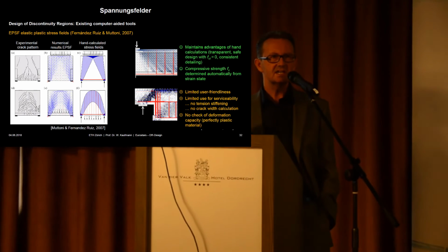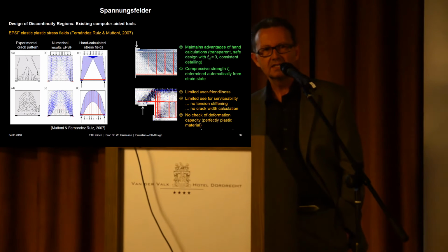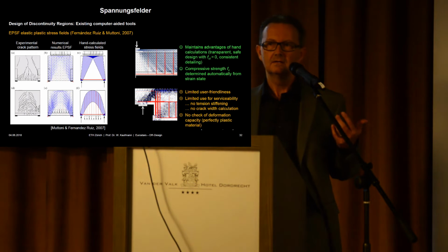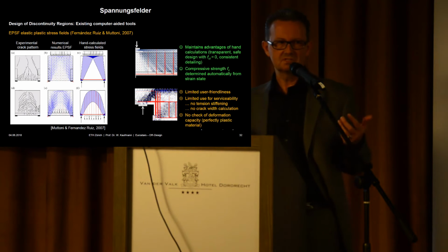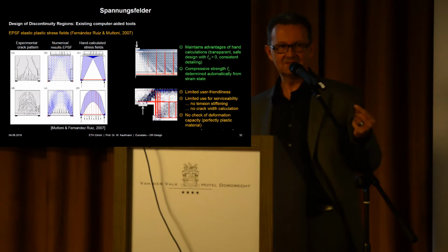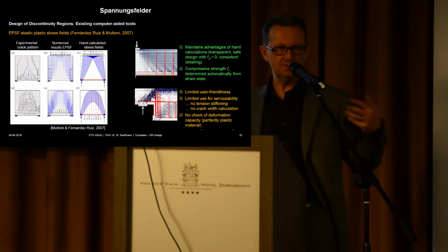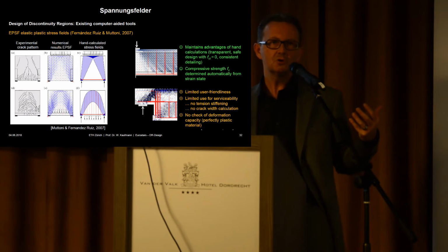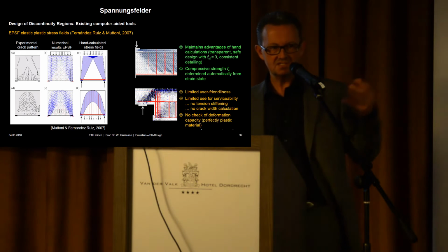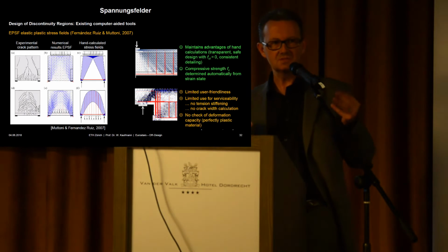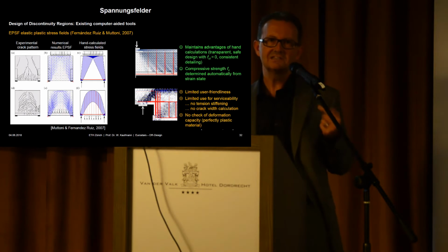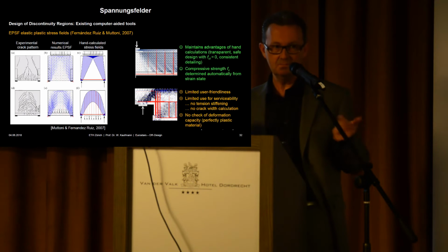Well, actually, we do a linear elastic calculation, and all these stress fields are stress assumptions. So they're possible, they're not deformation, sorry, that would be the finite element method, right? So if you do normal finite elements, you have deformation assumptions, possible deformations, and the right solution is the softest one. In this case, we have stress assumptions, and the right solution is the stiffest one. So the one not minimizing the strain energy, but the complementary strain energy. But as long as everything is linear elastic, that's the same.